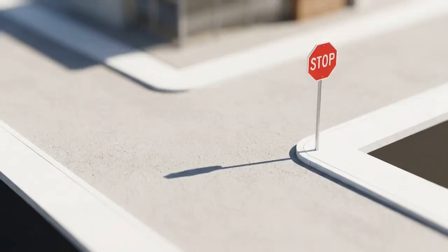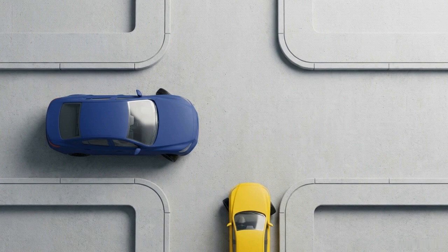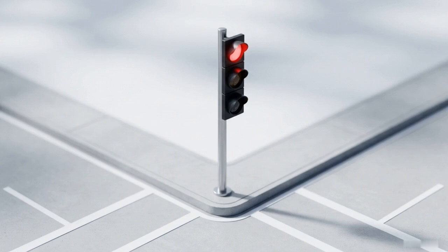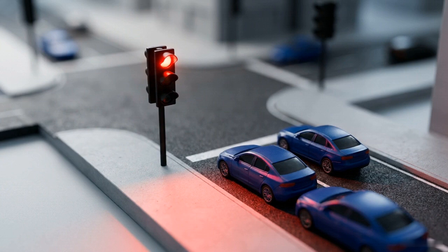At the base level, we utilize the standardized geometry and color of passive signs to regulate driver autonomy efficiently, solving minor conflicts without stopping momentum. When volume overwhelms that system, we apply the active compromise of signals, stripping away autonomy and using automated phases to trade travel time for right-angle safety.